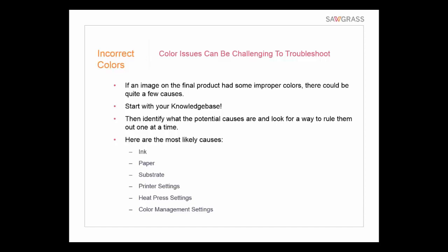Pressure. Changing your pressure can have an impact on the image as well, though in general, if you're using a good mid-range pressure, it works pretty well for most products. I would look at heat first, okay, and the timing as well. A lot of times the heat is the one I really go for first, to make sure that everything is in spec the right way.